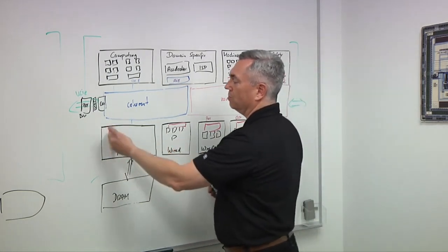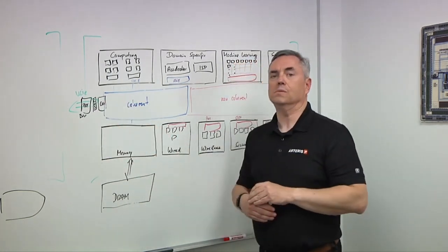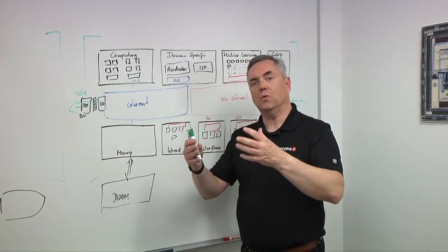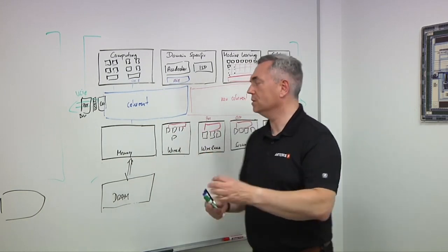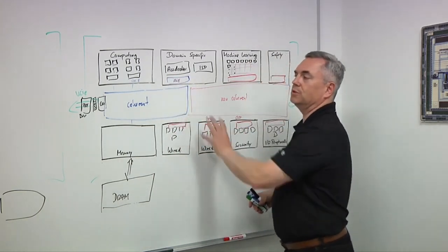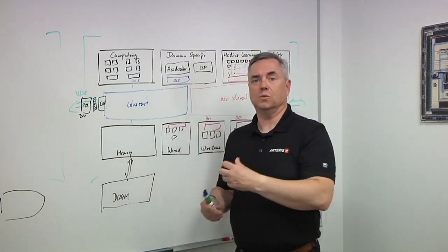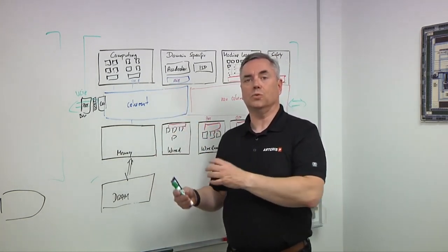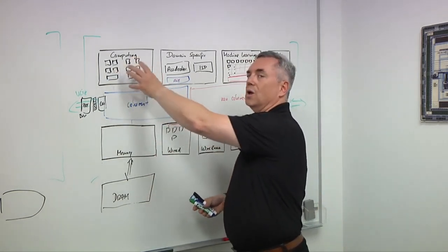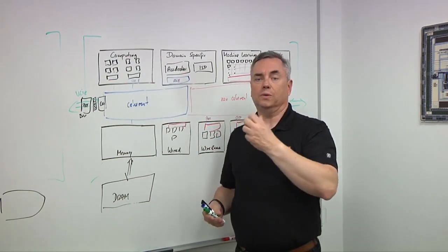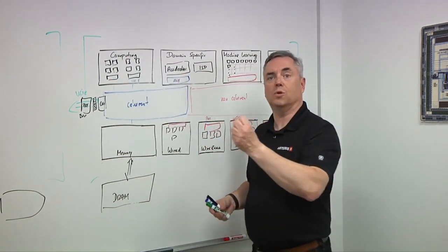Same things around the memory interface, the IOMMUs, how you deal with the memory interface. How do you do simple things in air quotes like interrupts? So you have these interrupt controllers that need to work, and that you have your RISC-V processors to react to them completely, right?